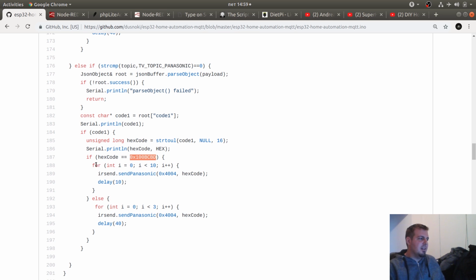So I did a for loop, where I send it 10 times with a 10 millisecond delay. Send Panasonic needs the pre-code and the hex code itself. So I send it 10 times with a 10 millisecond delay so that I can actually turn on the TV. And for the rest of the codes, I just send it 3 times, just in any case.